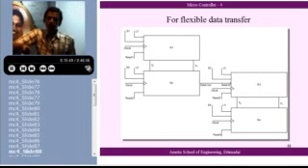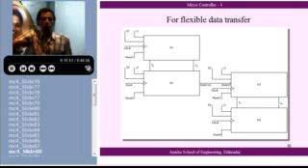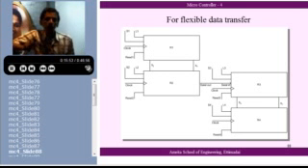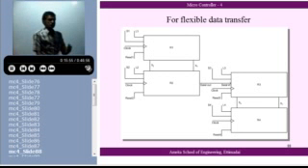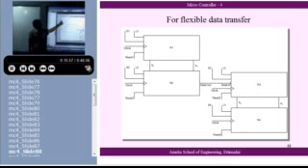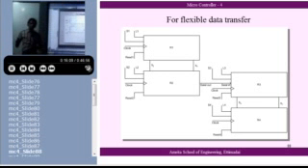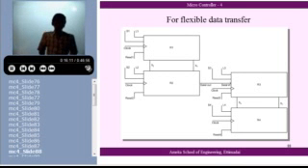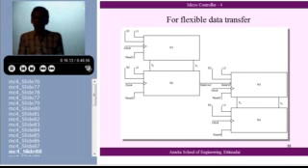To manipulate and get the necessary data, storage, transfer, shifting, all that I have to do is properly work these signals. This serial signal, load signal, read signal, all these are the control signals. All these control signals I have to bring out separately, and I ask you, what do you want me to do? You say you do this. I make them high, low, the way I want. And then give the clock pulse, the data will go in.